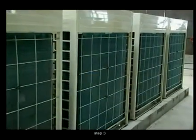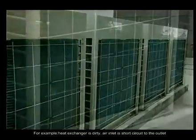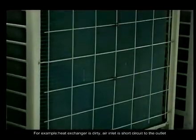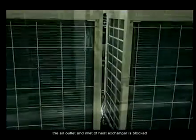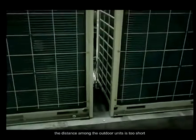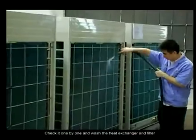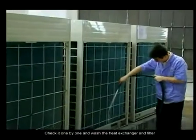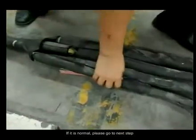Step 3. Check if the outdoor unit is not well heat transferred. For example, the heat exchanger is dirty, the air inlet is short circuited to the outlet, the outdoor fan doesn't work, or wind speed is too low, the air outlet and inlet of the heat exchanger is blocked, the distance among the outdoor units is too short. Check it one by one and wash the heat exchanger and filter. If it is normal, please go to the next step.